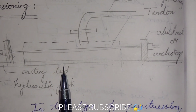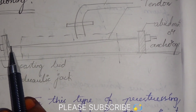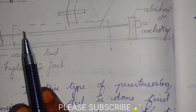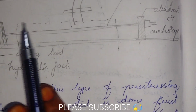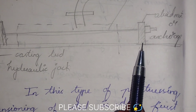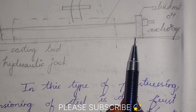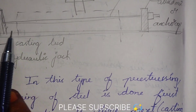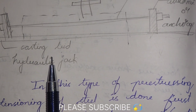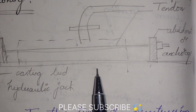What is pre-tensioning? Here the tendon is nothing but this wire. These are tensioned between the rigid blocks. These are the rigid blocks, directly cast on the ground or as a column or unit mould type. This is the pre-tensioning bed. The bottom one is the casting bed, or pre-tensioning bed, as we call it. All of this happens prior to the casting of concrete in the mould.